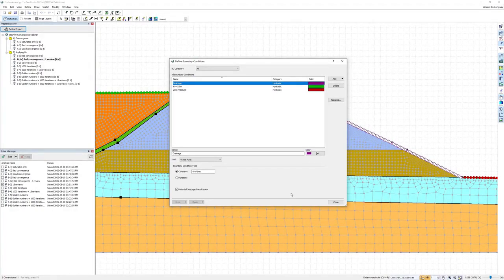In other words, when the solver starts, it doesn't know where the phreatic surface should exit the dam. So it initially assumes all nodes have the zero water rate type. It solves the analysis and examines the solution to determine if it is proper. If it is not, then it will turn water seepage off at some nodes and allow water out through the zero water pressure boundary condition type. It will solve the finite element equations again and repeat the examination process.